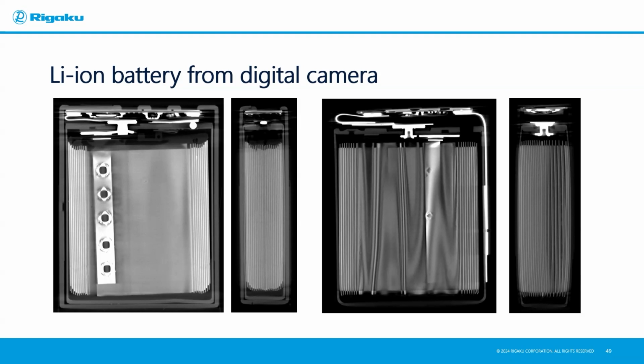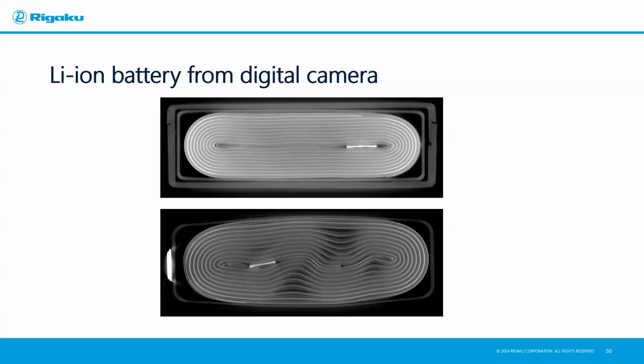If we look at a top-down view cross-section, it becomes even more apparent how this change or deformation happens across the battery. So the top is the good battery in this case, and the bottom is the bad, and we see that there's something happening throughout. And remember, I said that you get lithium accumulation, and that can cause stress. The layers start to delaminate, and you get these pockets or voids, and that's essentially what's happening in this case. And you can usually detect that by external view, because you might take a battery out of your device and it may look swollen.